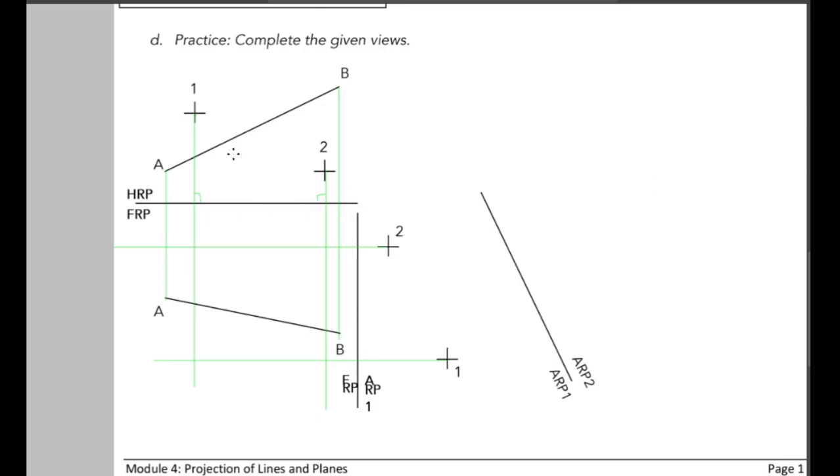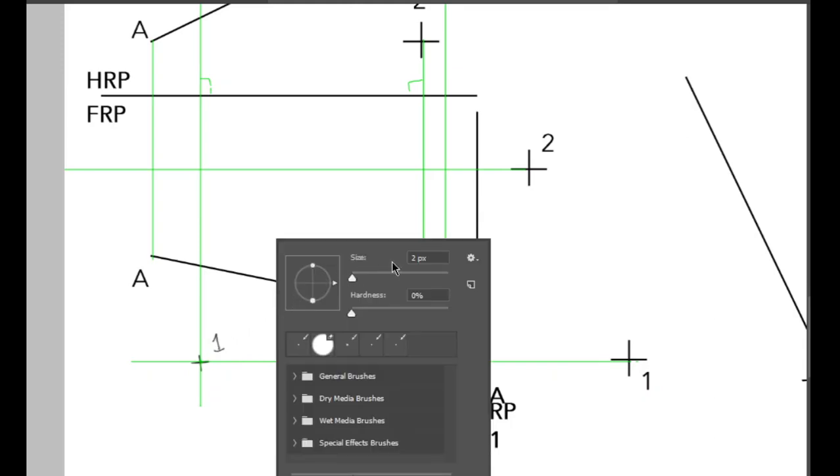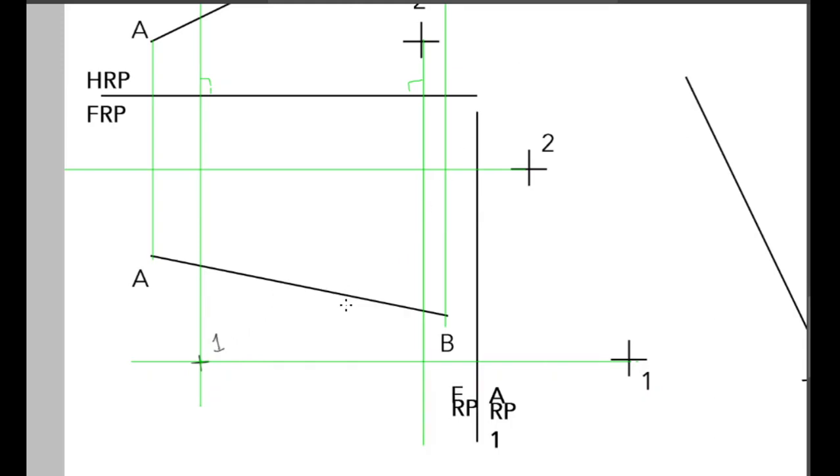But an interesting thing here is that this is the projection line of point 1, correct? So point 1 should be located somewhere here, but point 1 is also within this other projection line. So this intersection should be the location of point 1. Let me just label this.